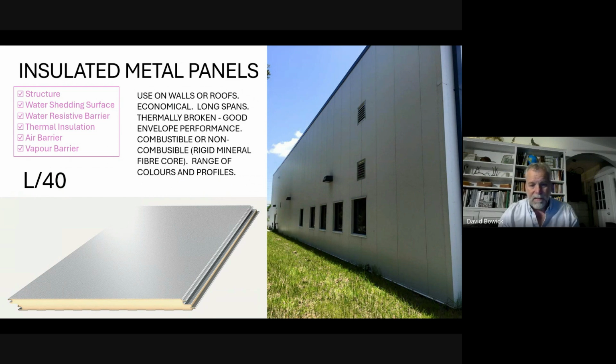We have talked about this. You see that it's thermally broken. Where those joints interlock, the steel doesn't form a continuous path from inside to outside. So it's thermally broken, but the joints interlock in a way that drains the cavity. Air can get past the first joint on the outside. There's a vertical cavity, and water runs down and out without penetrating through the second tongue and groove. So it's quite high performance, a perfect barrier drained cavity.